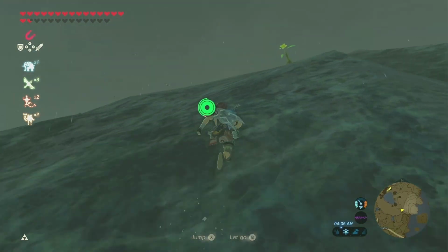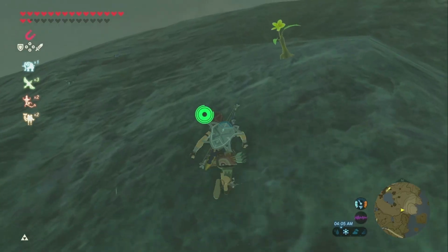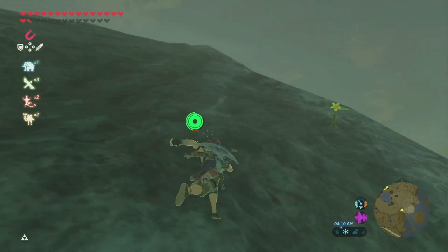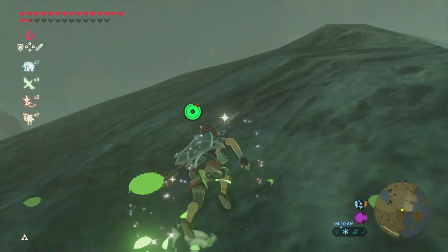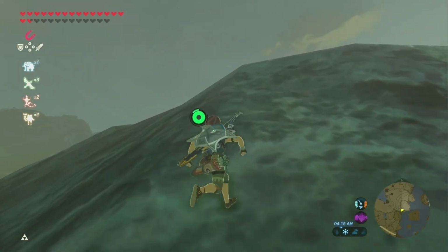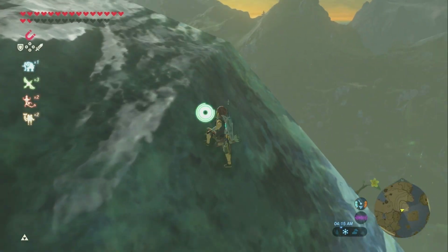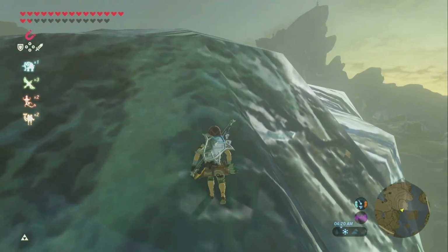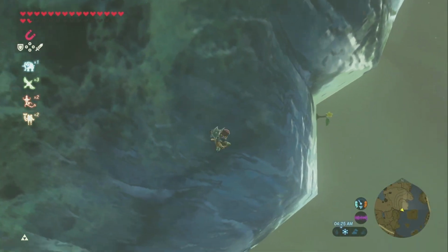Power vented water heaters draw in 2 1/2 to 4 times as much room air as there is exhaust product volume to drop the exhaust air temperature below 200 degrees Fahrenheit or 93 degrees Celsius. This doesn't add to the efficiency of the system in any way, since we are removing air from the house that we've heated to 70 degrees Fahrenheit, 21 degrees Celsius.